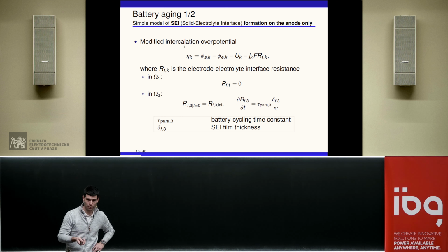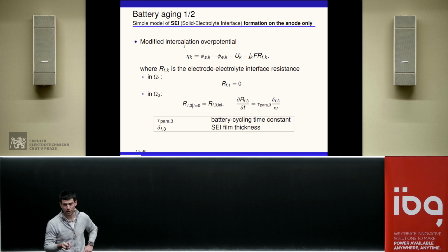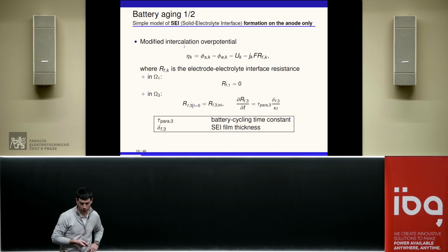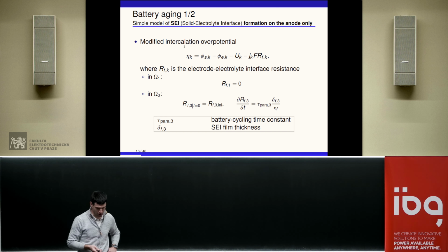But for our applications, which are mostly the high-performance batteries found in electric or hybrid electric vehicles, the internal resistance is actually much more important, because even though you can maintain most of the capacity, once the internal resistance increases, the batteries can no longer be used for electric vehicles. They can, of course, be used somewhere else. For example, we know that there are tendencies to use depleted HEV batteries for electricity storage, for example, in households.